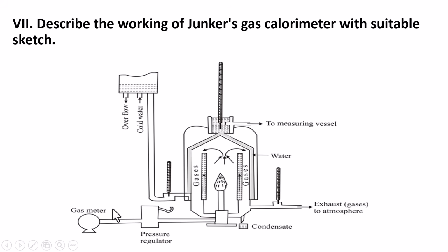Actually, what happens in this case is, to measure the calorific value of a gaseous fuel, the gas will be burned inside the chamber. Due to burning, it will produce some heat energy. Whenever water is circulating through the surrounding of this chamber, the water absorbs the heat energy of the fuel.